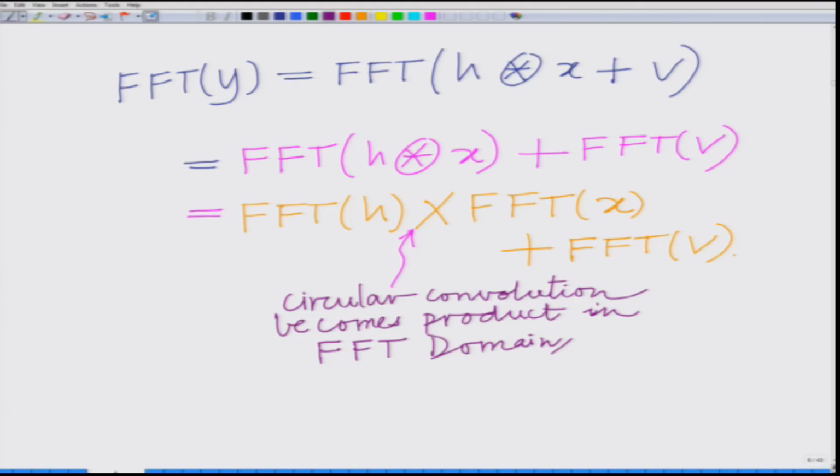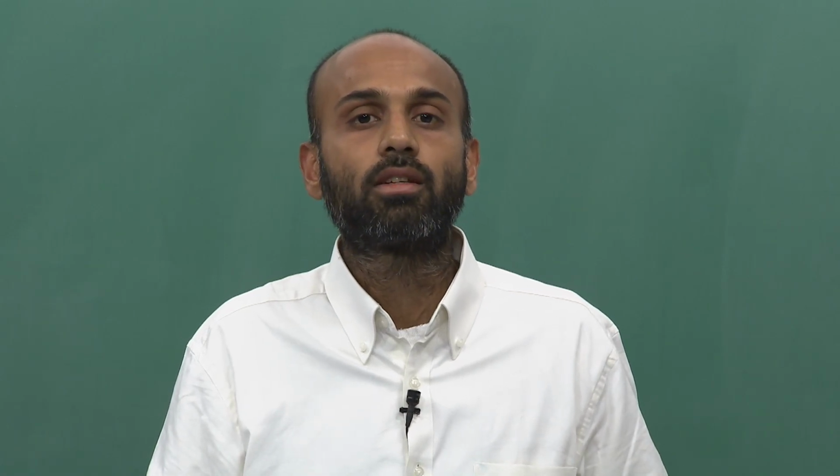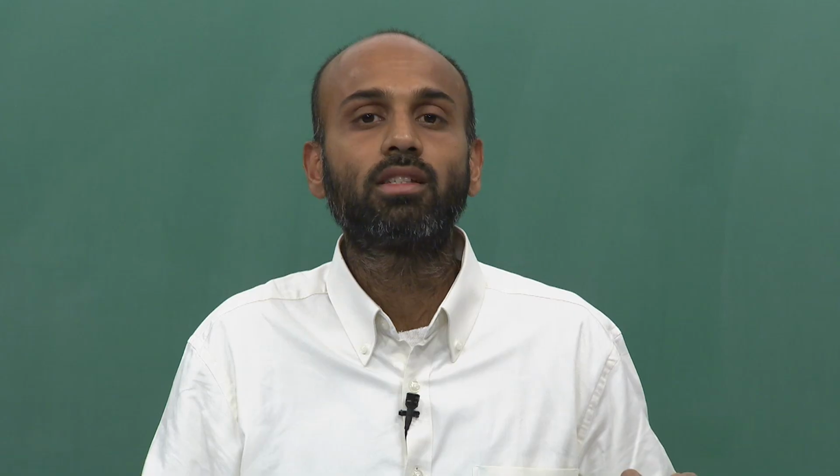Alright. That is the interesting aspect of OFDM, where we have taken a block of symbols, capital X0, X1, X2, X3, performed the IFFT, or IDFT, to generate the samples. To the samples we have added the cyclic prefix, and now at the output of the intersymbol interference channel, what the channel is performing is equivalent to a circular convolution.